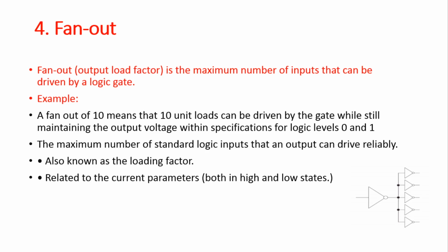It is the maximum number of standard logic inputs that an output can drive reliably, also known as the loading factor, related to current parameters both in high and low states.